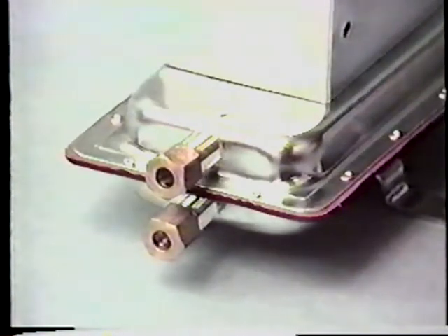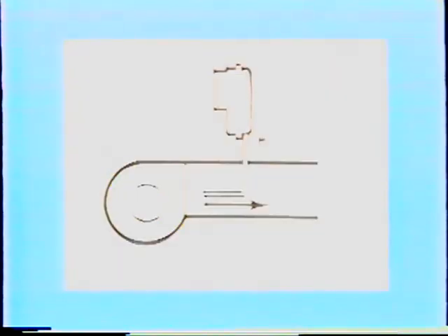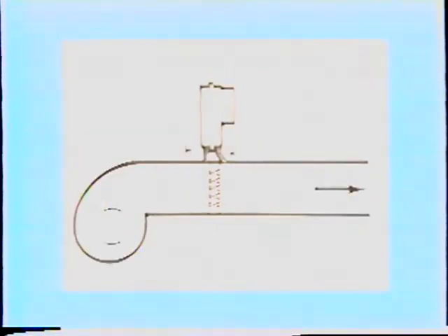The device has 2 pressure input ports, a high and a low. When sensing a positive pressure only, the high port needs to be connected to a sampling tube, leaving the low port open to atmosphere. When monitoring filters to initiate a dirty filter alarm, the high port is piped on the upstream side of the filter, and the low side is piped to the downstream side of the filters.